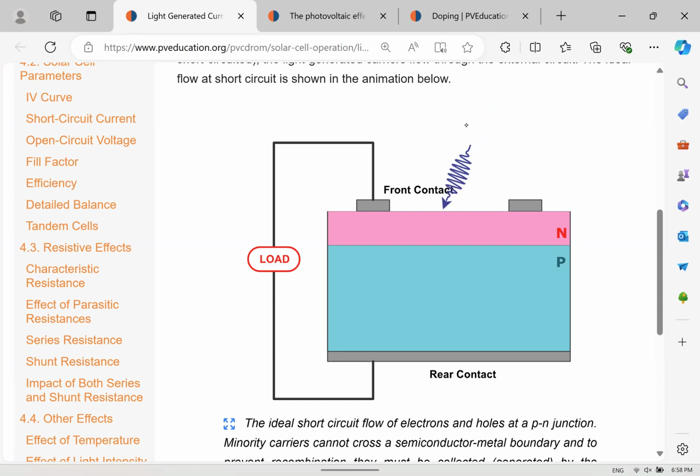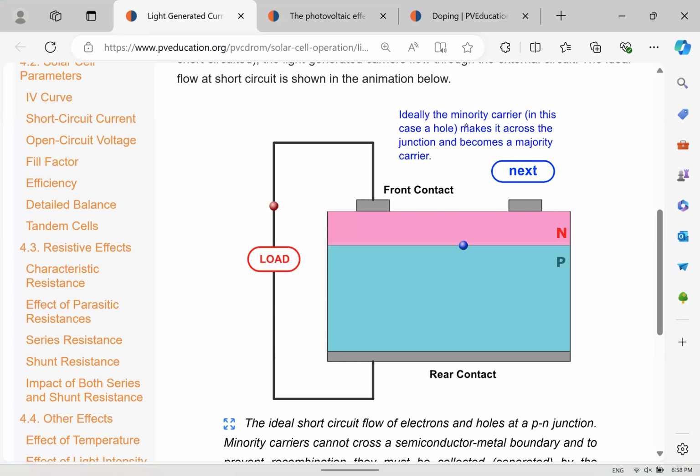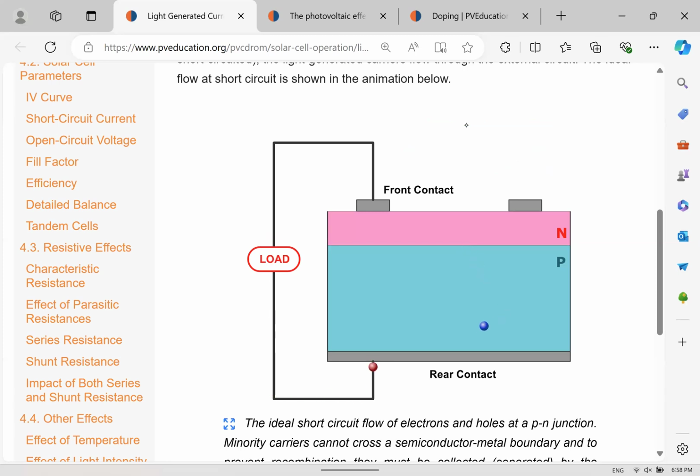You can see that we have our photon coming in there. It's incident upon the semiconductor material. That has created the electron hole pair that we were talking about. And now the electric field that is established and completed through the connection from the N-type material to the P-type material is allowing the electron to move through the circuit. And after it's done moving through the circuit, it will come back over to the hole, combine, and the process will end up repeating again, where we have that photon generating the electron hole pair, and then in the end, the pair ends up combining again, and so on.